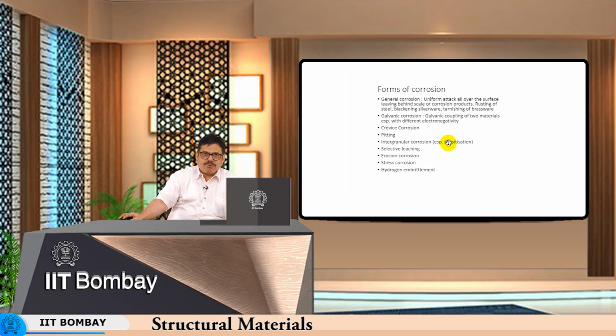So, what you believe is that it is strong enough, but in that time hydrogen diffuses to the point of maximum stress and then results in a brittle failure there. So, brittle failure is very sudden, it propagates very rapidly, and therefore, there is a sudden precipitous failure taking place due to which there can be an accident. So, hydrogen embrittlement is a very dangerous situation.